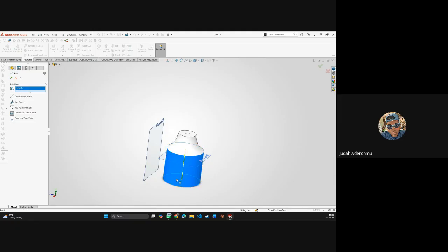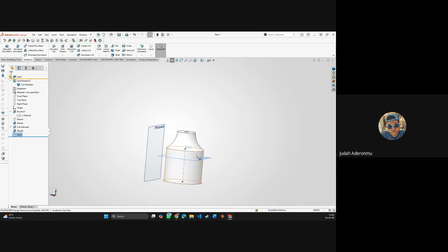Once you click on one face, it will automatically select this cylindrical conical face for you, and it is going to create this axis in the middle. If you have created this axis, for example, now go back to revolve cut. Oh, yes, there's another thing I was trying to explain. The axis is not going to show if you created the axis after you first created the revolve cut. So for example, if the revolve cut already existed before the axis, then